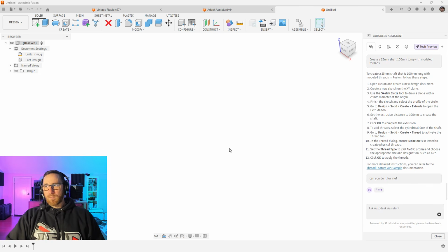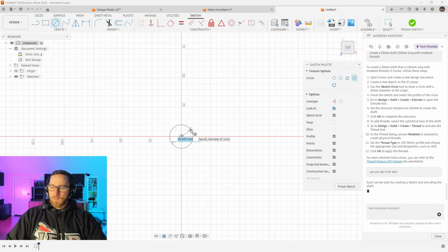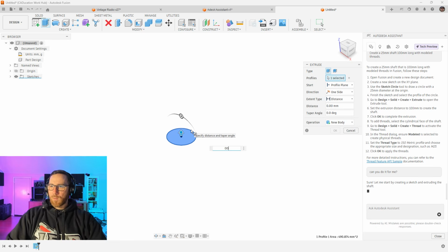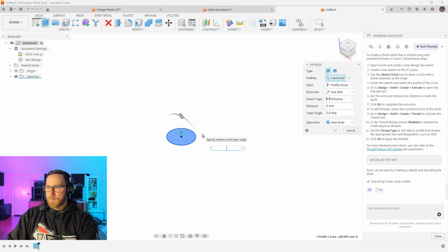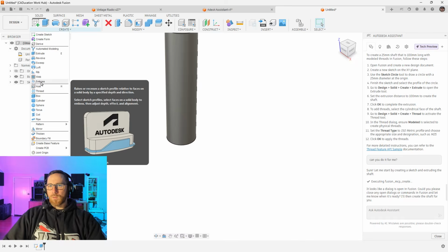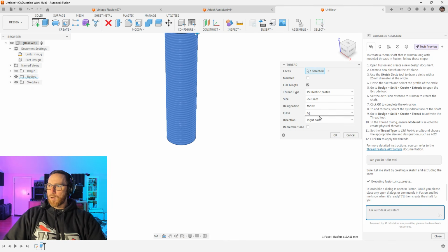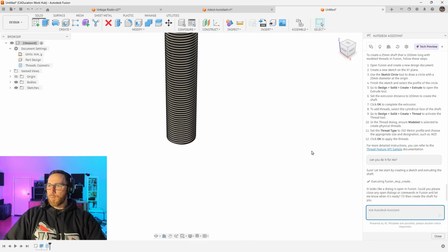I had one question, like a help file question, that came back pretty quickly, and another one that took like 30 minutes before it came back to me with an answer. So I do think that performance is going to be key in order to have something like this provide any value. Now it's thinking. At this point, if I were to do this, I could just do this: 25, hit extrude, type 100, go to my thread tool, click on that. It's going to automatically pick that. I'm going to go modeled, boom, done, right?